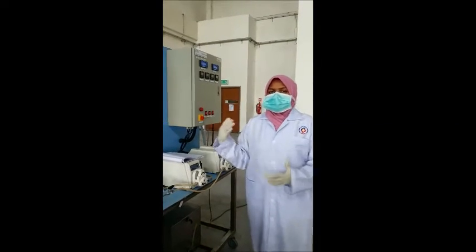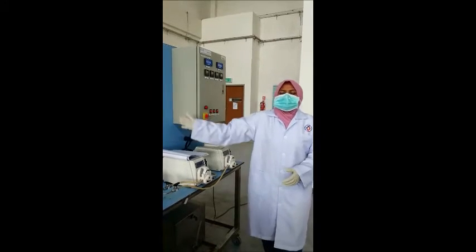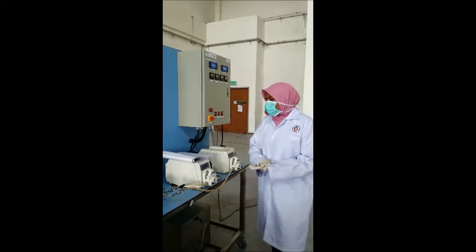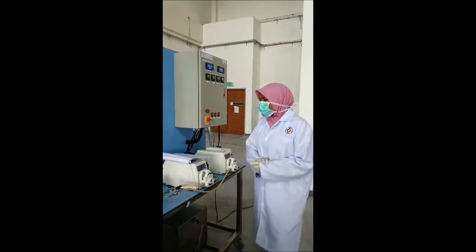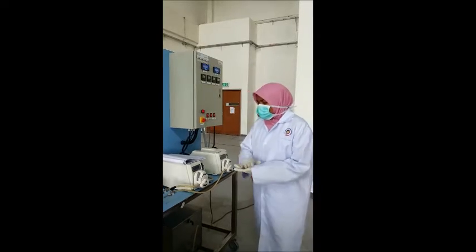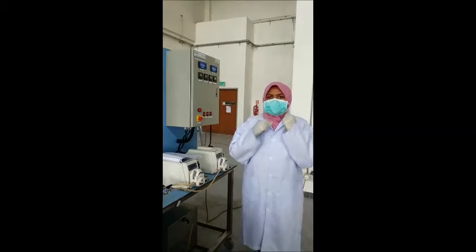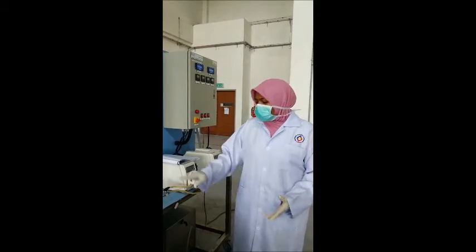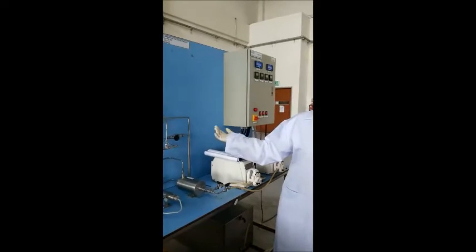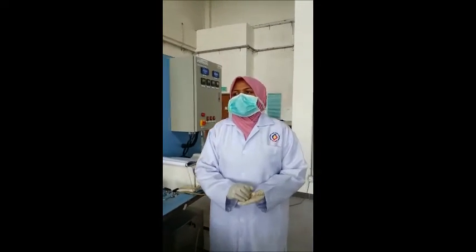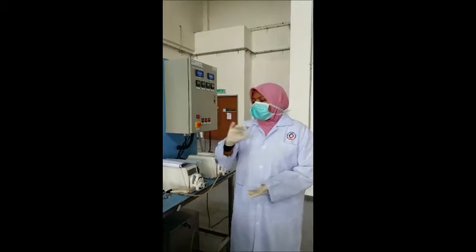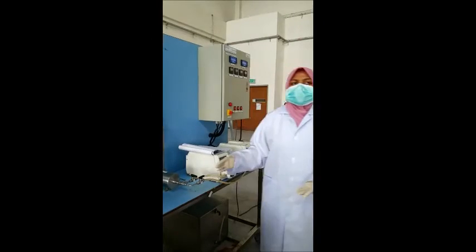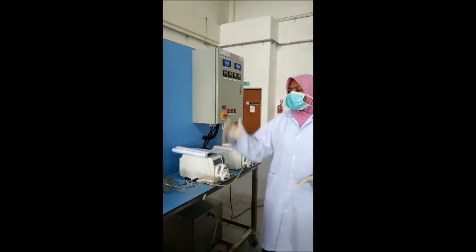After we start up and now have 20 liters of ethyl acetate solution, we need to start the experiment to study the effect of temperature on the reaction. But first of all, we need to ensure that our valves are in the correct position. In this experiment, we should only open the valve V2. V2 is at the tank, and it allows the solution to enter the system. Then V5, which will direct the water from the pump, and V7.